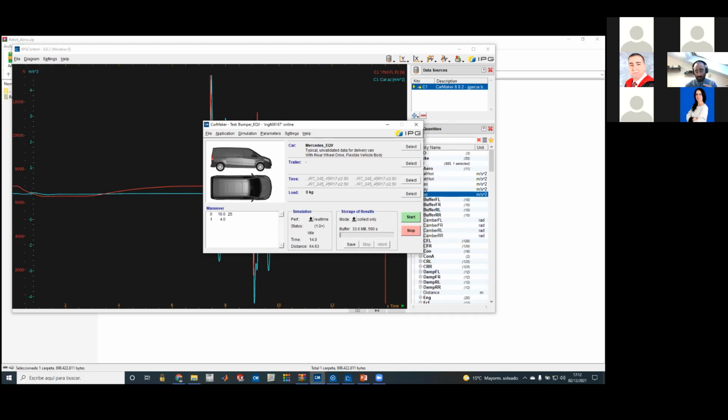And linked to the comment on vertical and lateral, this is the key point. If I'm facing the camera, let's say the X axis will be through the camera, the Y axis will be the transverse direction, and Z will be the vertical. So the key point is the rigid body motion of the car body on the suspension.